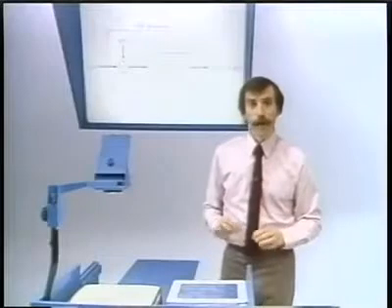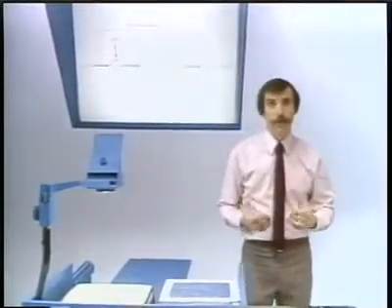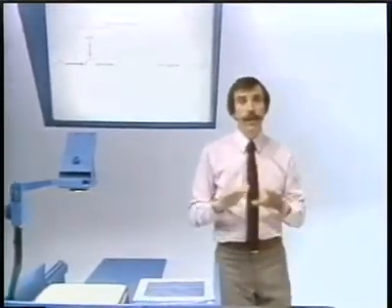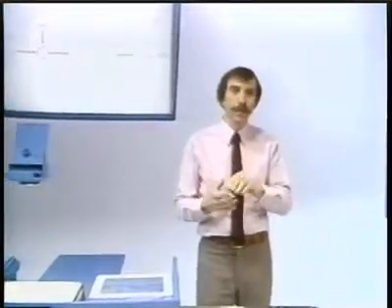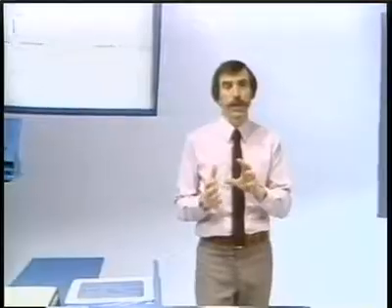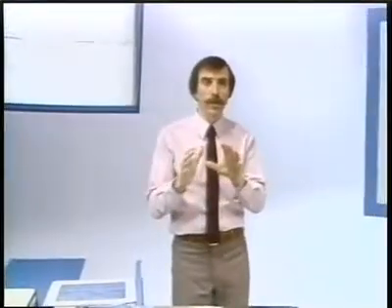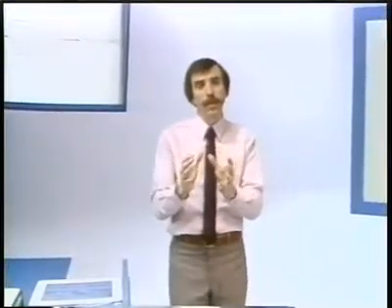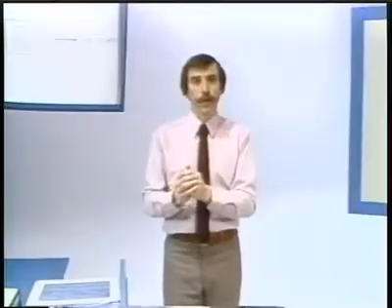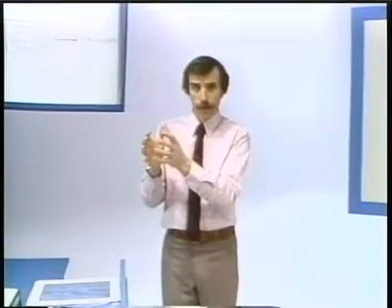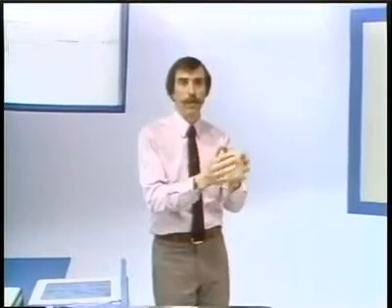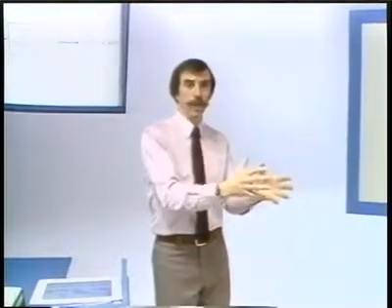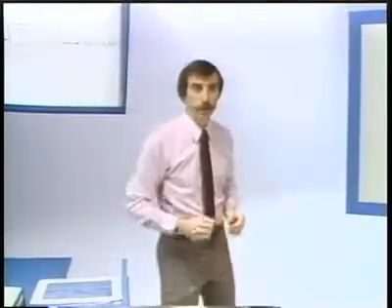So what I'd like to do as a first step in understanding this process is to analyze it, in particular with our attention focused on trying to understand what the relationship is in the frequency domain between the discrete time Fourier transform of the sequence, the discrete time signal, and the continuous time Fourier transform of the original unsampled and then the sampled signal.